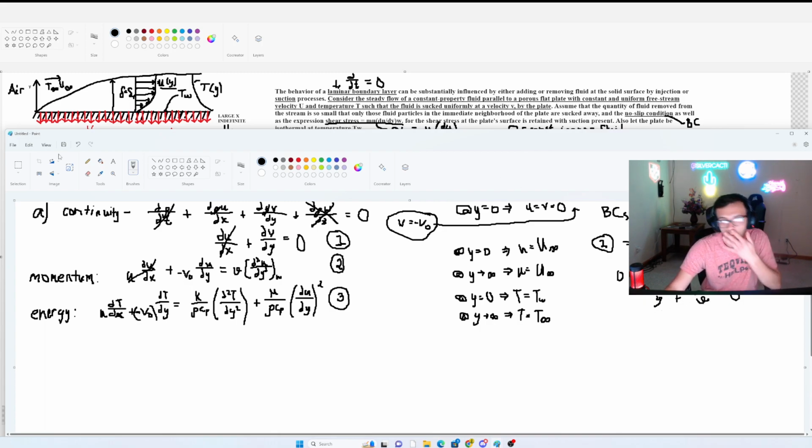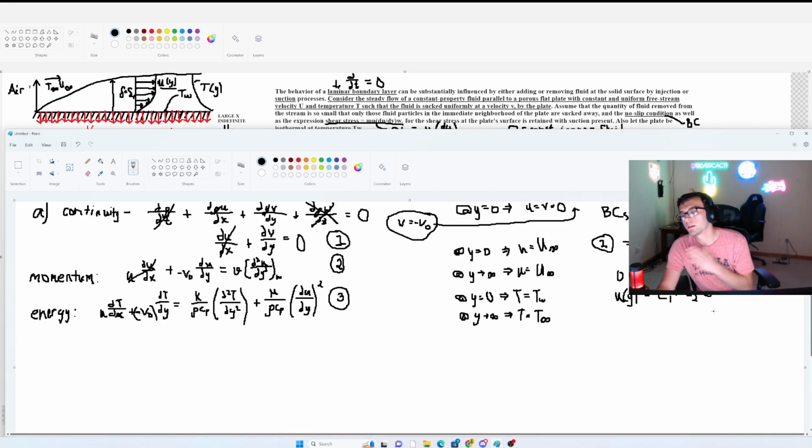But you have to solve it as a differential equation, so it's a little more confusing than that. For differential equations like this, you know this is a solution. So the solution for a differential problem, u, which is u sub y, the thing we're trying to find, is going to equal c1, a constant, plus c2 times the exponential of minus v sub o over viscosity times y. For a differential equation like this, that's the format of it.